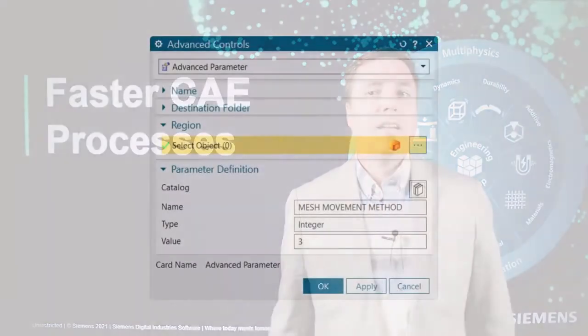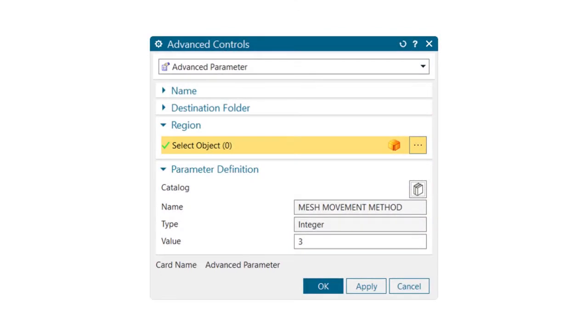For fluid structure interaction applications, the fluid mesh deformation can be difficult to compute for some types of simulations. In this release, a new robust mesh moving method helps speed the process. A new inverse distance weighting method and Laplace smoothing equation method are available as advanced parameters for the mesh movement method.